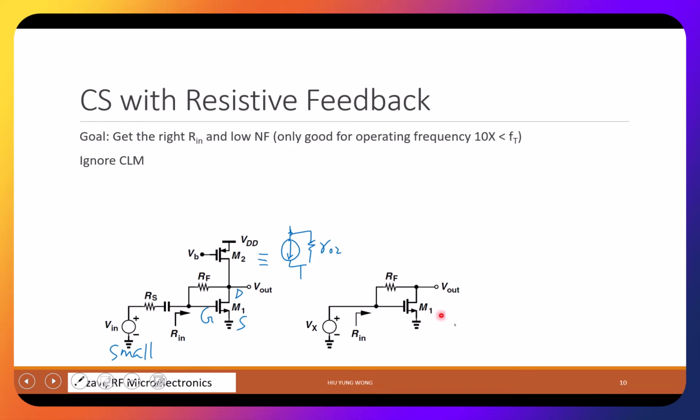And then here draws the small signal model. Now somehow we here assume RO is very large. So we ignore it. And because this is a current source, in small signal, what do you do? Open it. You open it. Then you only have RO2. And now I assume RO2 is large. Then just like open it. So everything is gone before the V out. And here we short this resistor, right? Now, actually they did not. We should also draw RS, but we can do that later.